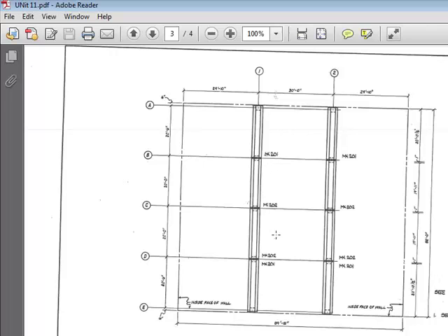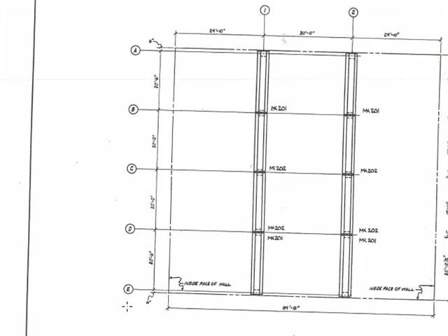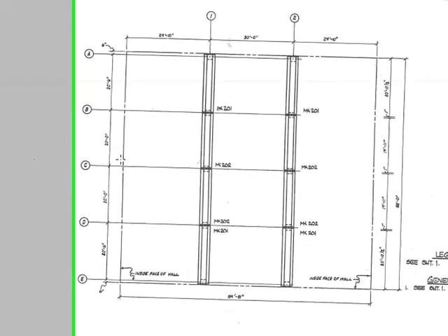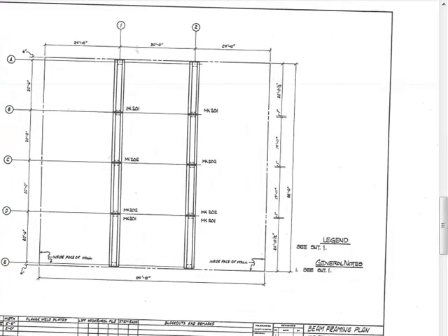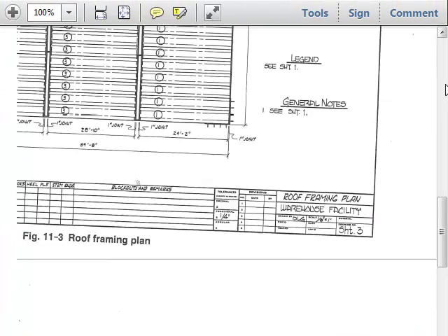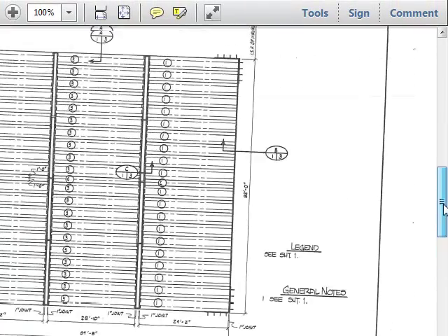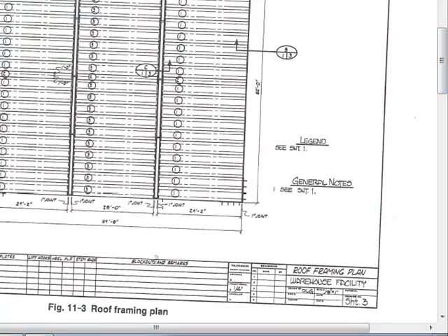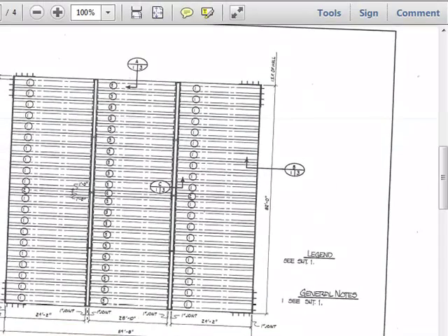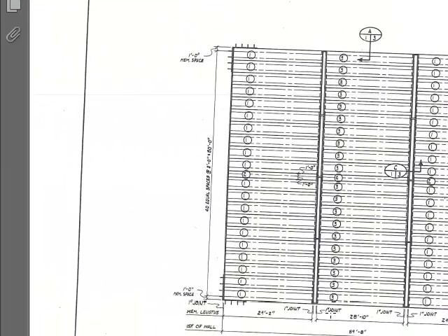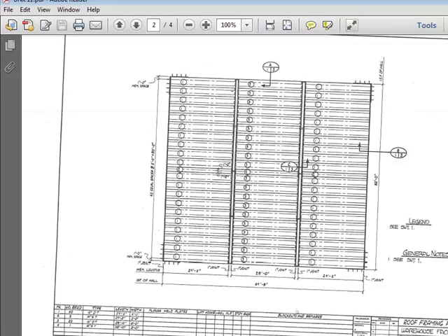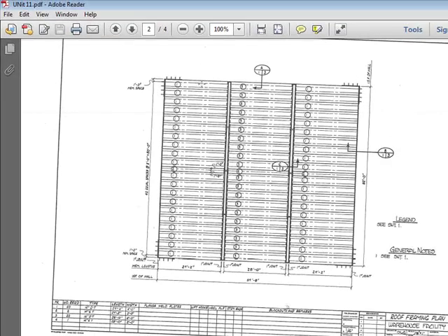You're going to draw a column plan and a beam plan for your assignment. So this is what these two things would look like. You have your column lines and your dimensions and the face of the outside wall, if that's given. And then the other types of plans would be a roof or a floor framing plan. You've got your beams below, and then these double T's are going to sit on top. So when they're all stacked up together, you have a flat surface.